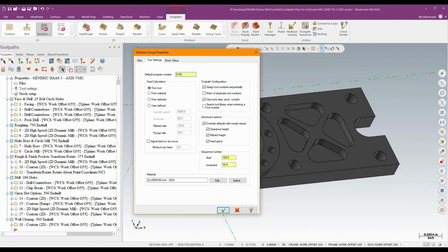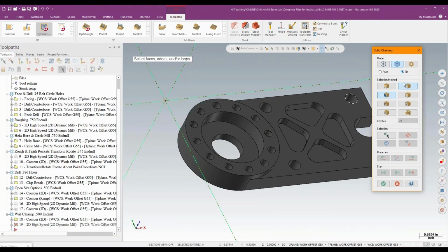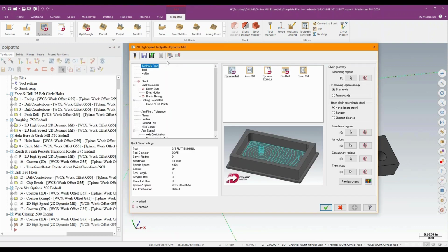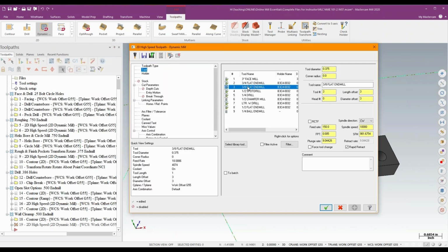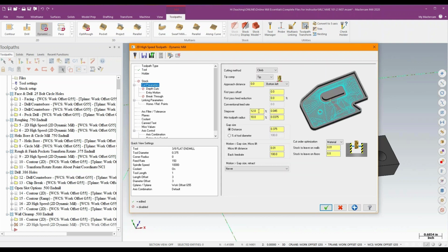So with that checked, when I do something like a dynamic mill, and we'll just do a real simple inside strategy here. So I'm just going to do that pocket right there with a 3/8. When I grab tool number 3, there's my spindle speed, and there's my feed per tooth. So it drops that in immediately as I select that tool. When I go down to my cut parameters page, I should see my XY step over percentage automatically drop in at 12% or whatever I had it set for. Those are 3 things I don't necessarily have to remember to do every time. It's just closer.